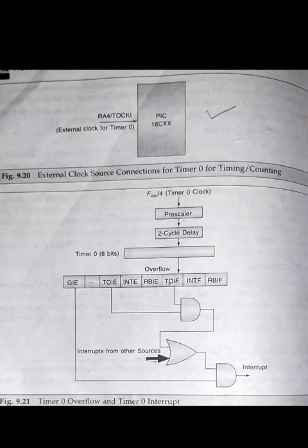Programming timer 0 allows handling longer interval events with only an 8-bit maximum value of the timer counter. Further, the external clock frequency can be higher than the device frequency. The maximum frequency that can be used as a clocking source for timer 0 is limited to 50 MHz.